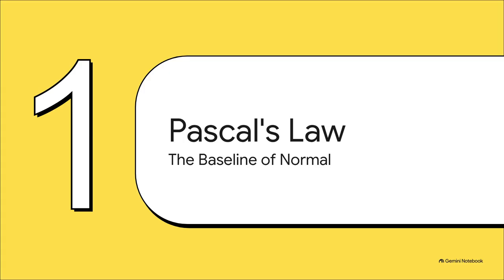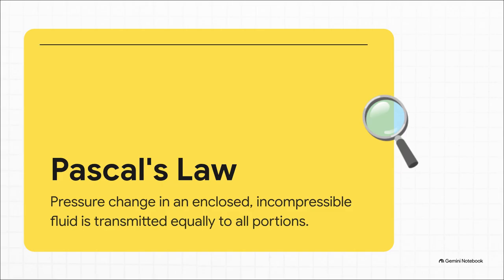The power of Pascal's law, or as I like to call it, the baseline of normal. Okay, so to truly appreciate the bizarre extremes of fluid dynamics we're going to cover today, we first have to establish our baseline. The absolutely crucial takeaway of Pascal's law is that liquids, like oil or water, are basically incompressible for everyday engineering. You just can't squish them into a smaller volume. Because of that, any energy you put into a sealed fluid system has to be transmitted instantly, equally, and totally undiminished everywhere inside that system.